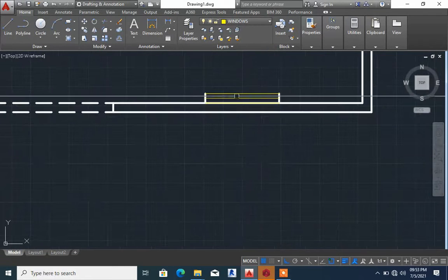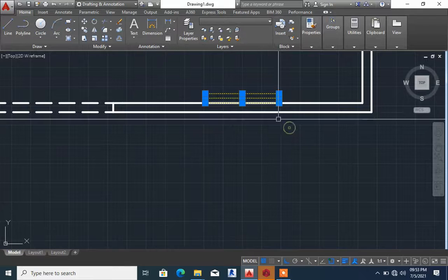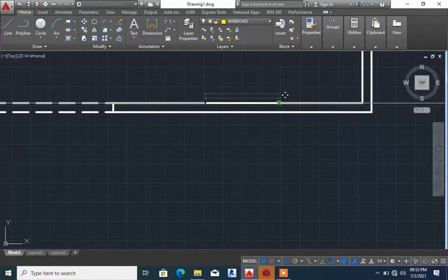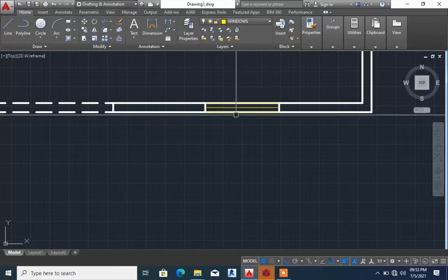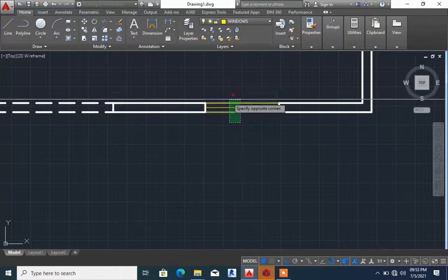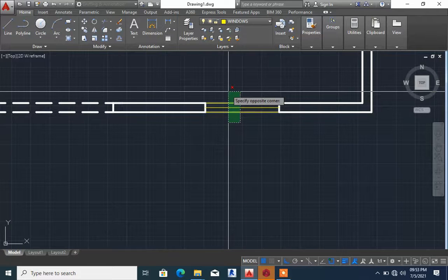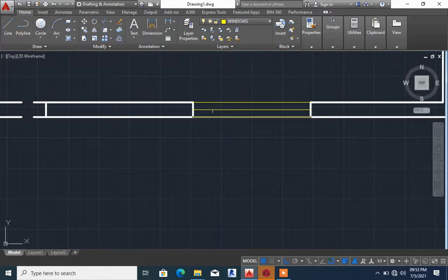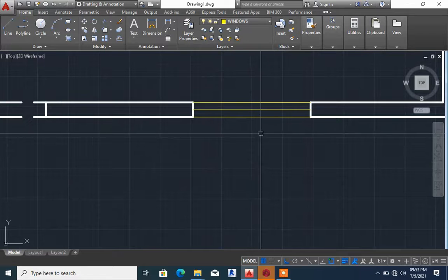Having dropped it here, you can now highlight it again, then move it from this edge to this edge. With that, you can now trim, click on TR and right click and trim. You see, these ones did not trim because they did not intercept, and these ones that got intercepted, that entered inside this window, are the ones that got trimmed.